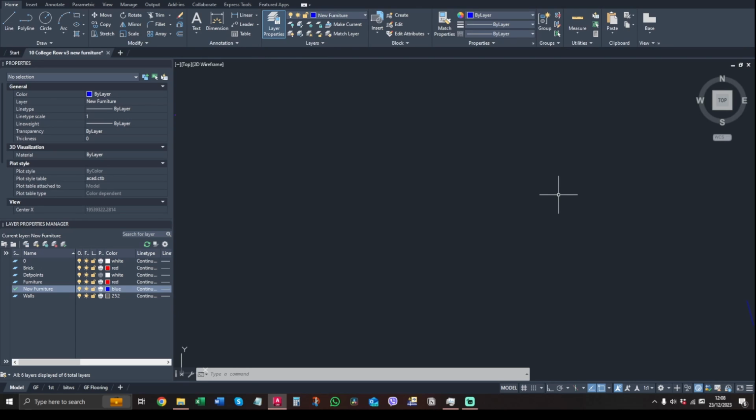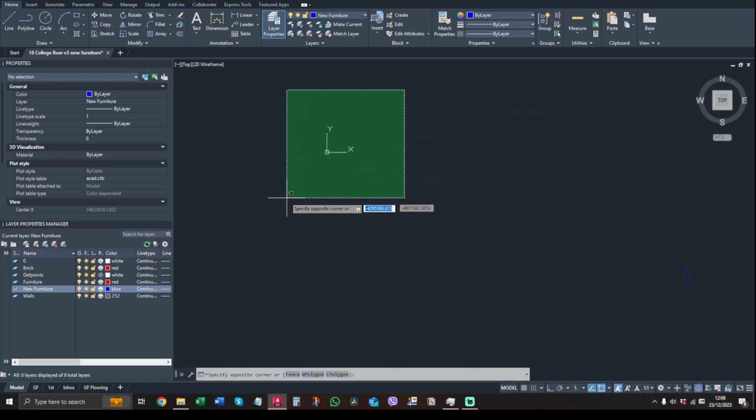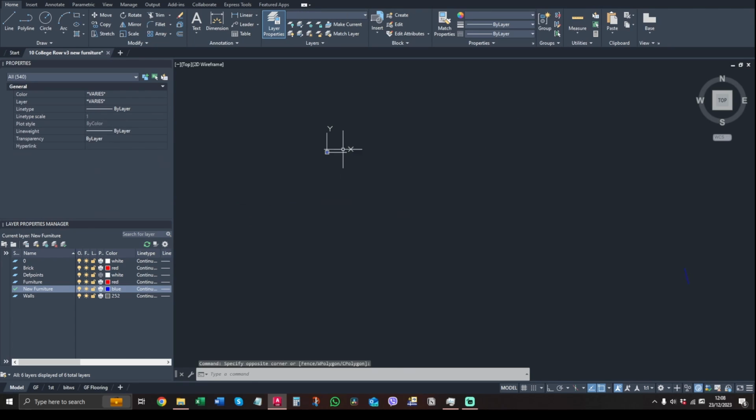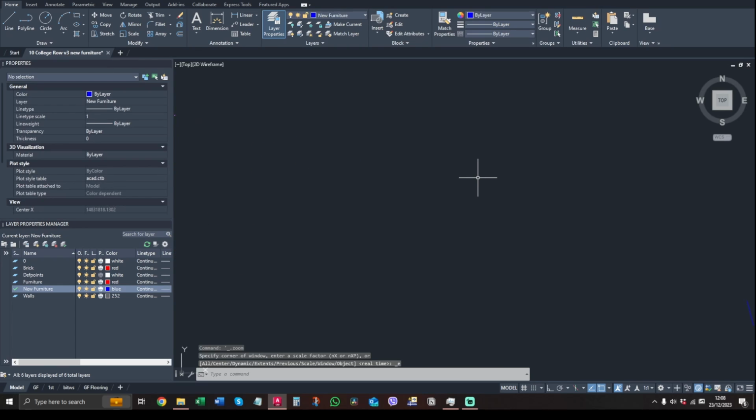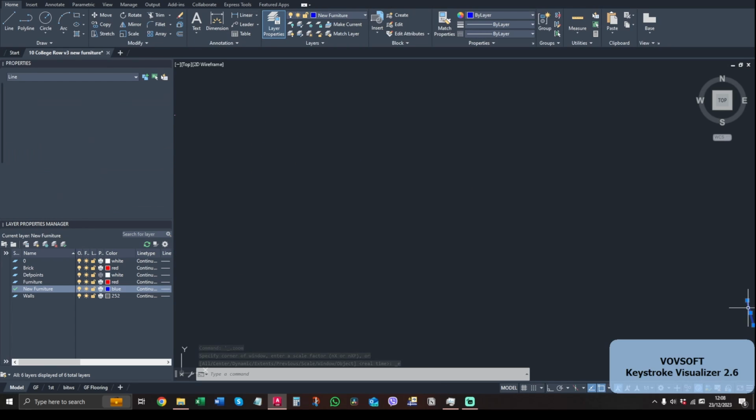When this happens, what's usually causing it is that you've got things drawn in model space very far apart. Sometimes this happens when you import things or when you explode blocks. There's lots of reasons it can happen. And what you'll find is, over here, if I select things there, I've got my original drawing there, but if I middle mouse again, what you see is there's a line here.